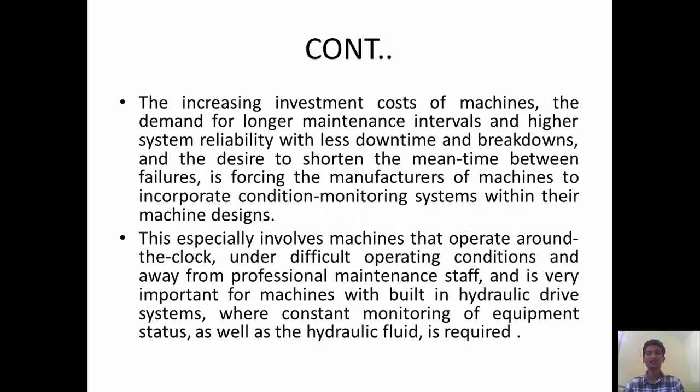Nowadays, with the increasing investment cost of machines, the demand for longer maintenance intervals, higher system reliability, less downtime and breakdown, and the desire to shorten the mean time between failures, manufacturers are forced to incorporate condition monitoring systems into their machine designs, especially for machines that operate around the clock under difficult operating conditions, away from professional maintenance staff. It is very important for machines with built-in hydraulic drive systems, where constant monitoring of equipment status as well as hydraulic fluid is required.